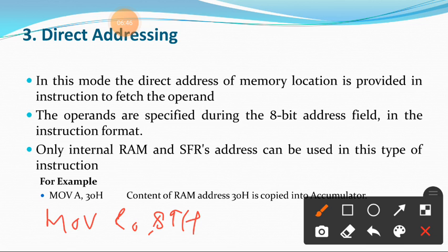Here the address 89H means it is a special function register, the TMOD register address. The content of the TMOD address will be copied into the register R0.